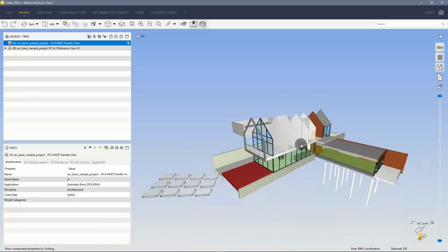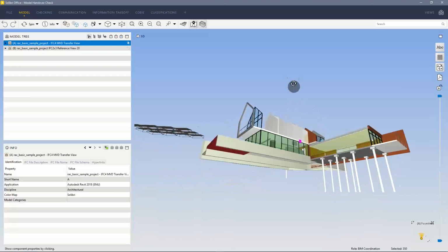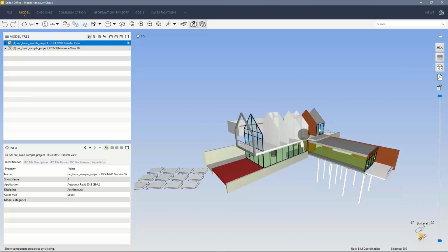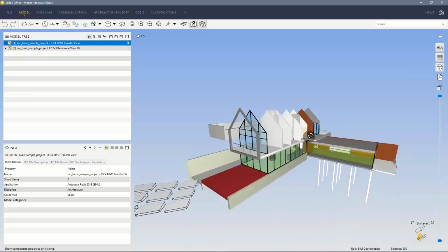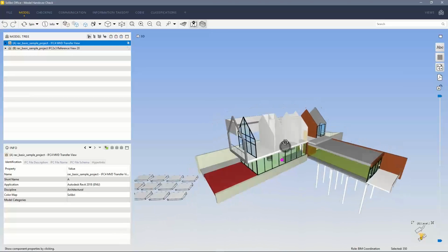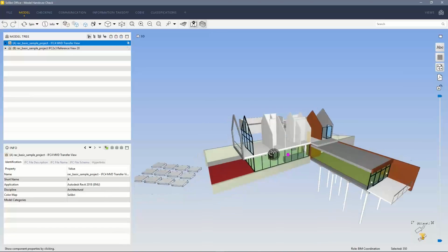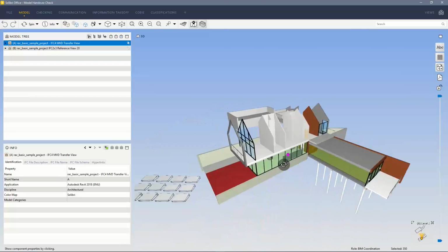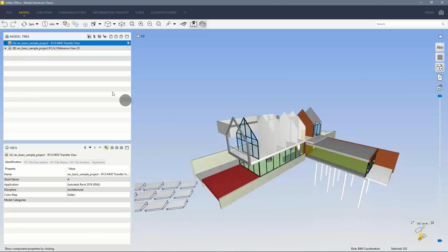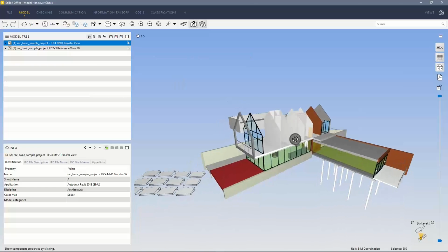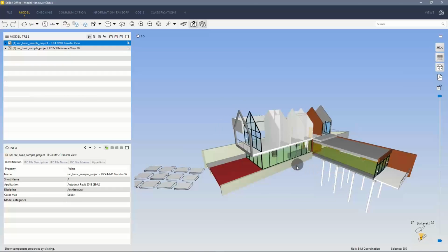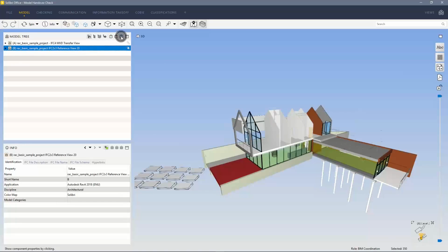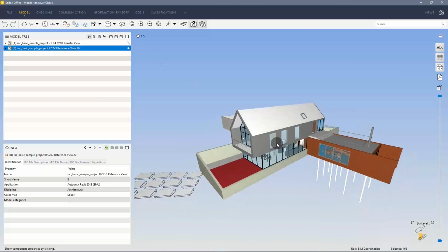I'm also aware, and that's something that we checked last week, that Revit at the moment is not certified for IFC4 exports. So it does a pretty good job, but it's actually missing quite a few bits and pieces. The reason why those bits and pieces are missing will be evident once we check the other IFC that I've converted there. Because of this, I'm actually going to use IFC 2x3. Now, this one here actually brings in all the geometry,